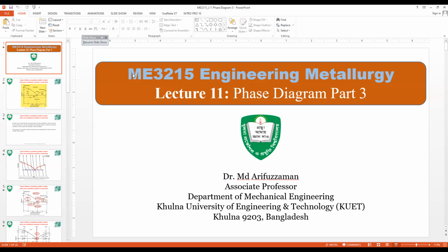Today, in the last class, we studied the type 1 phase diagram, how to determine the chemical composition of each phase and also the relative amount of phases. That means how much solid is present at a certain temperature, and then in that solid, how much part A or how much part B is present.